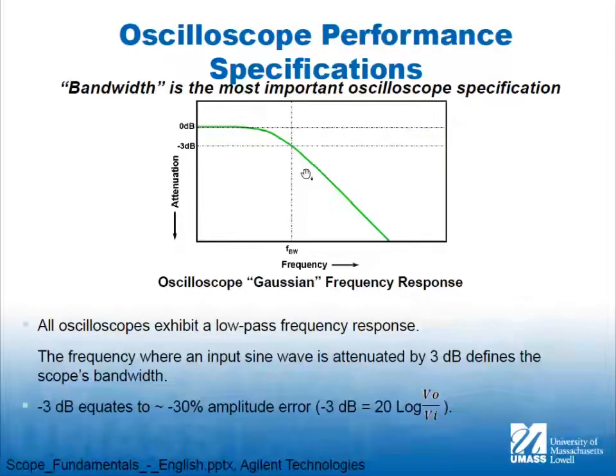at that point. So you don't use a 20 megahertz scope to measure a 20 megahertz signal. You need some headroom. Sometimes the people who sell scopes say it's a 5x difference. So if you have a 20 megahertz scope, the maximum value that you can rely on is 4 megahertz. Of course, they're going to tell you a large number. 2 or 3 is probably good enough, meaning 2 or 3 times the bandwidth. So if you have a 10 megahertz signal, you need a 20 or 30 megahertz scope.